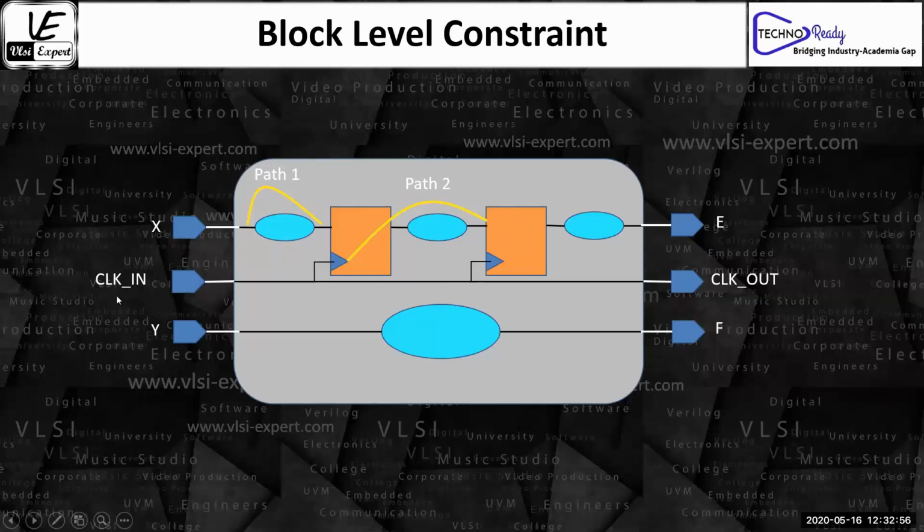Now, basically, the idea is to define it somehow in a language so that your tool is able to understand all these timing issues. That is your goal, writing a constraint. Now, what happens next is we have a block here where there is no flip-flop capturing anything. How do we write a constraint for such a thing? There is just combinational logic here.